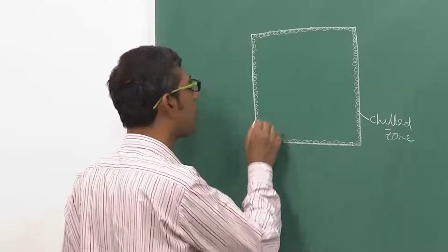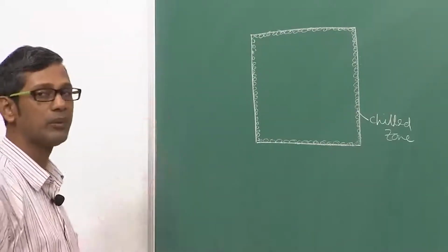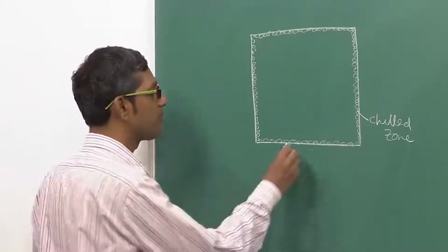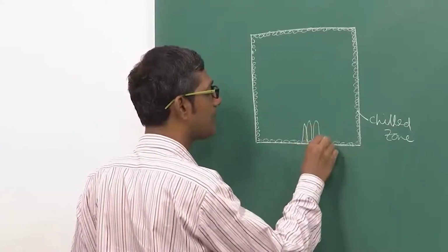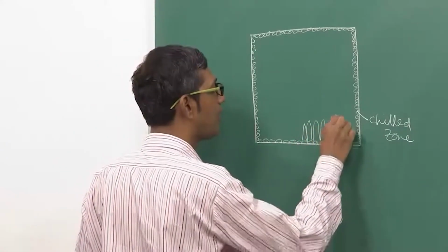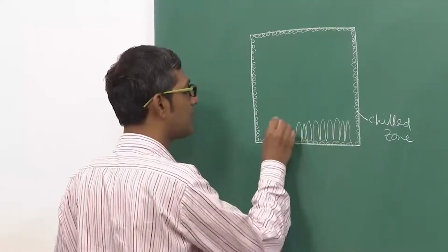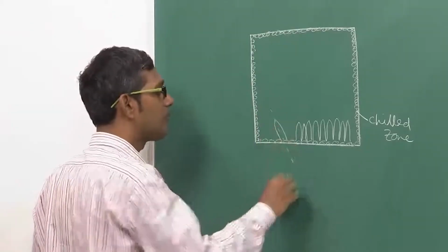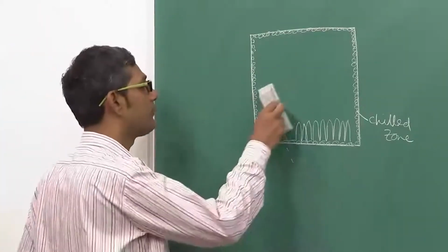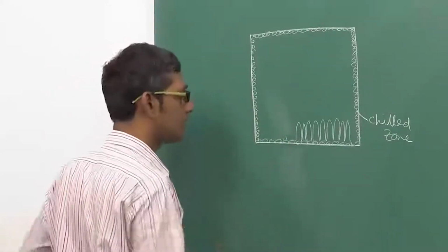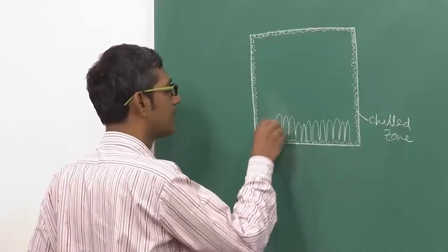The crystals which form on the walls at a small size will all try to grow into the liquid, but as heat transport becomes primarily important, only the crystals which are columnar like this will win over the others. If there is a crystal which is going like that, the heat transfer may not be happening along this axis, so it may not be the fastest one, and therefore it will die out. That is why these crystals will not stay. Okay.